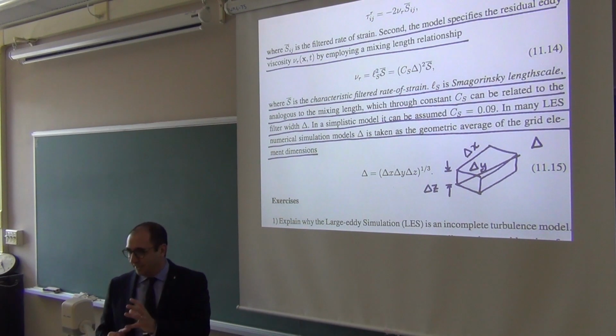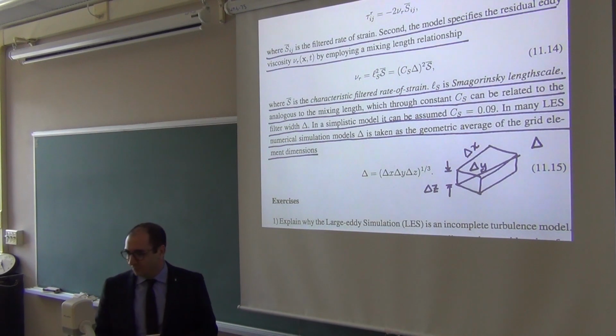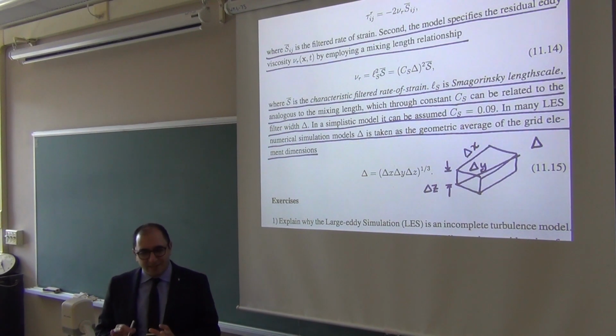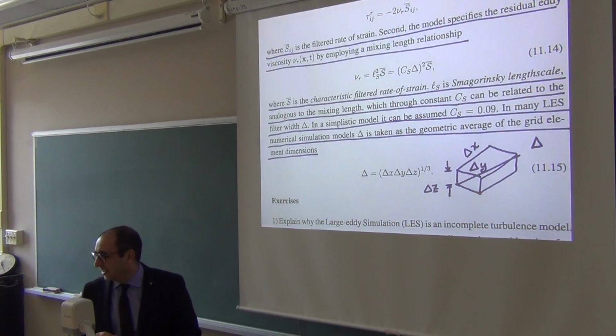You could be running RANS by LES. Some people run LES, but they're actually running the RANS model because they make oversimplifications and then do averaging right out of the bat, and then use a very coarse mesh. So things get really shady quickly into the unknown. So be careful of what you're doing.